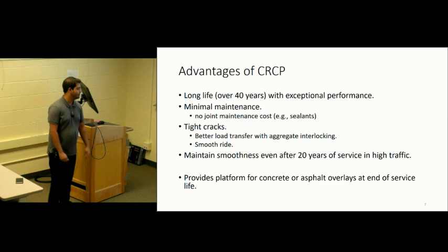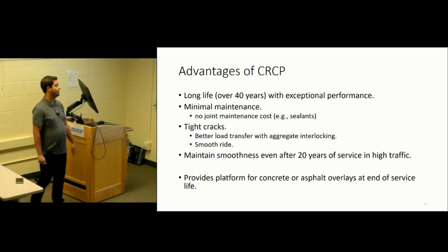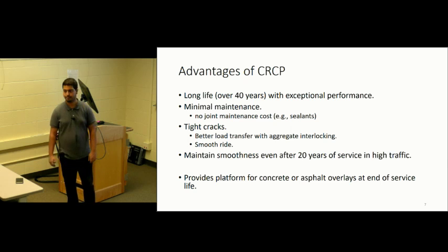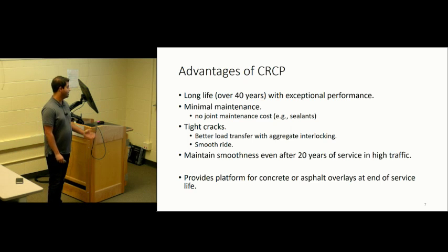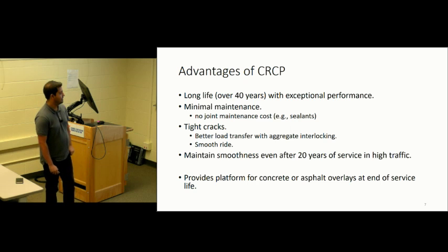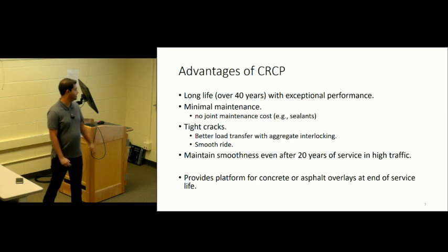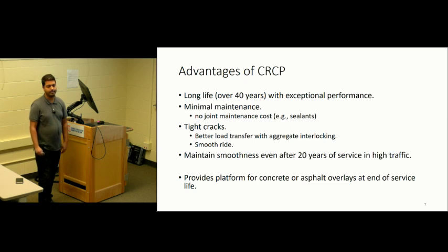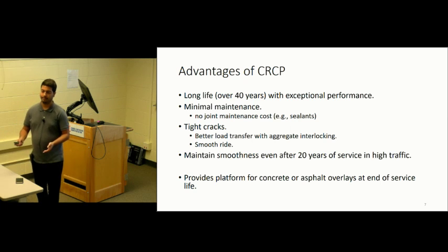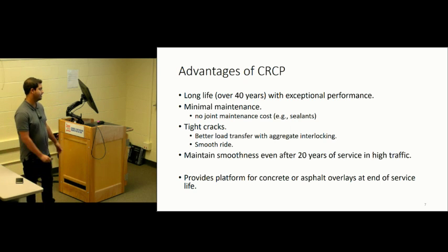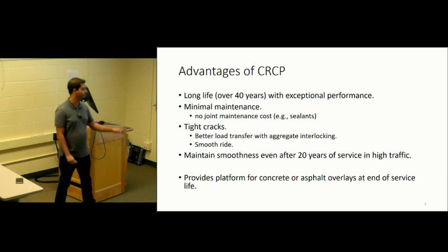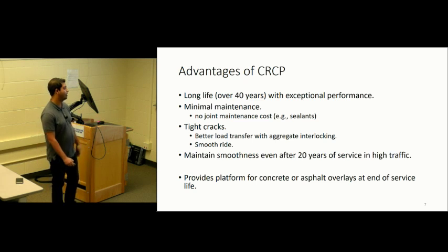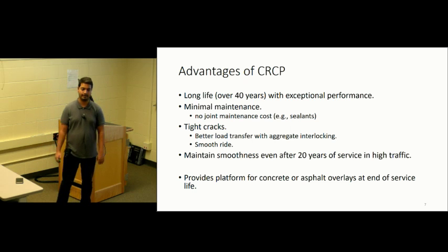And LTPP data shows that smoothness is maintained even after 20 years of service in high volume traffic. So it's exceptional that CRCP provides this. And the other thing is that any pavement comes to the end of its design life. At the end, CRCP provides a very suitable platform for an asphalt overlay, or any concrete overlay, at the end of its life.